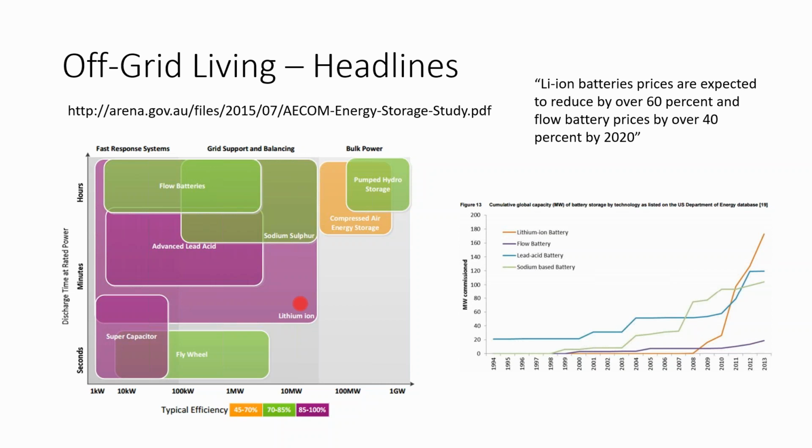But in the middle of the United States, you might have a bill like we'll look at in a little bit, where the kilowatt hour component is at avoided cost at 2 or 3 cents a kilowatt hour, and 90% of the bill is in the kilowatt charge.